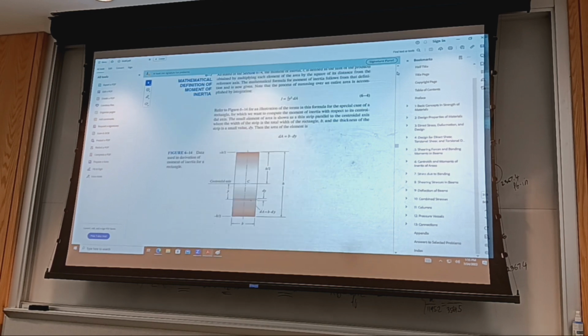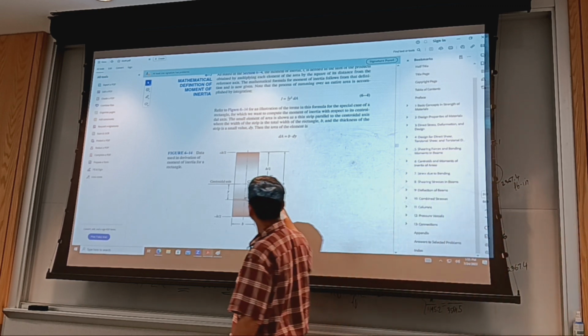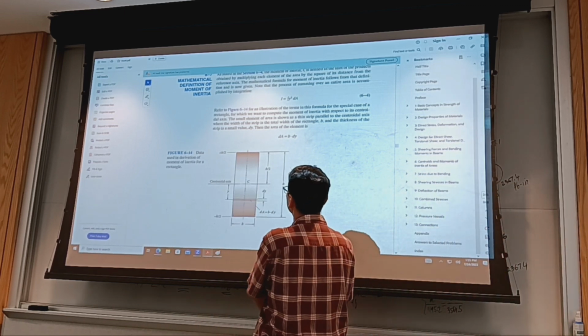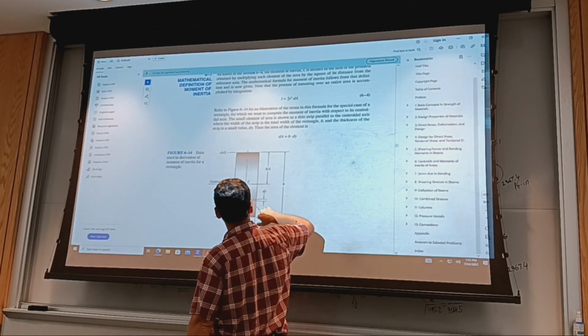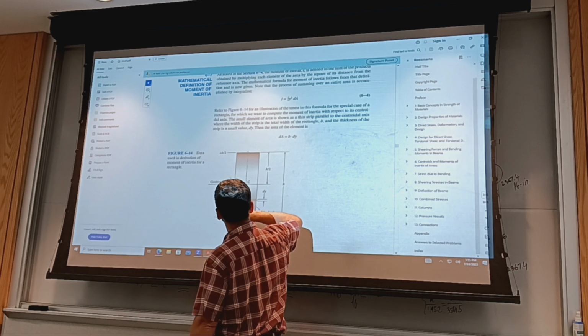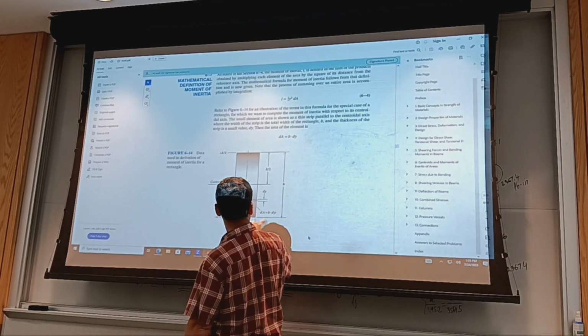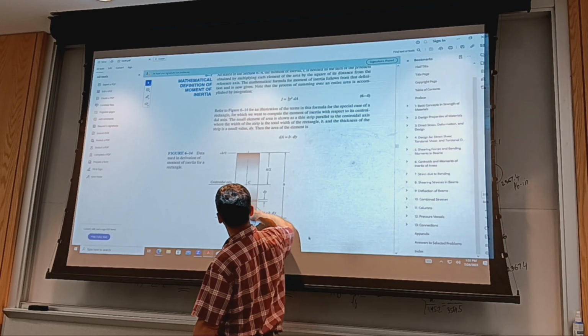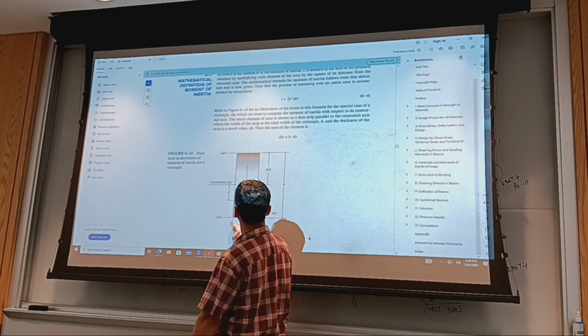And yeah, the things that you've seen in statics, I'm not sure if it was an excuse to apply integrals from calculus. So again, the definition of the area moment of inertia is distance squared times area. What would be the area? We scan with stripes, so dy times the constant b.